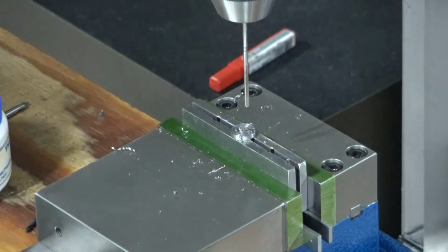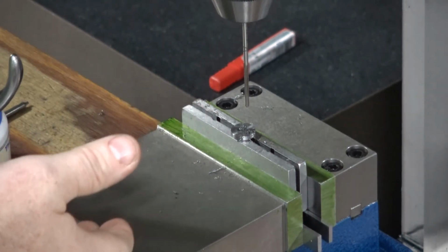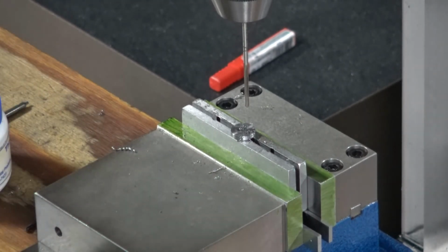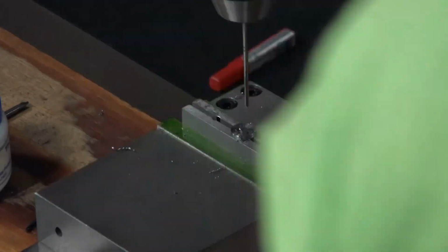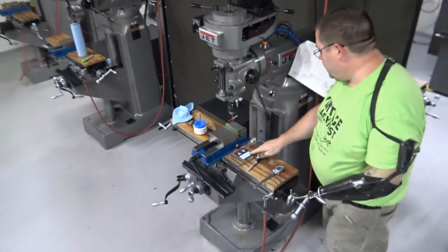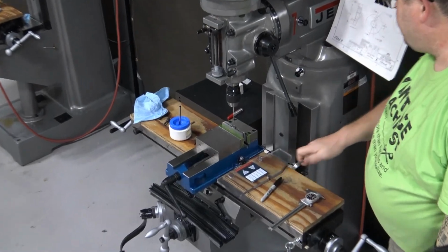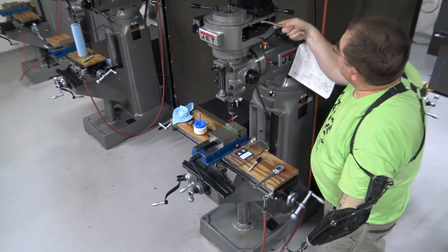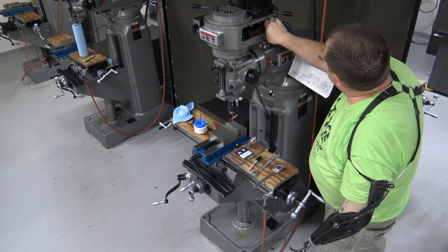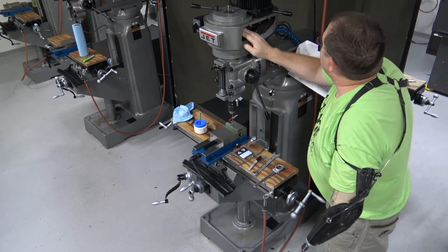I want to reduce my RPM because we said that we want to divide our calculated RPM by 2 or 3. So I'm going to get around the 1,000 RPM range. Let me walk through here real quick. I see on my chart that 1,000 RPM is step 2 on the pulley. 775 would be low range, which would be an acceptable place for me to be at. Let's go ahead and change this while I'm in the midst of it.